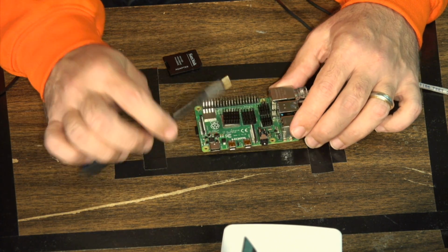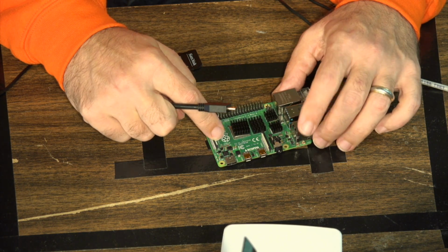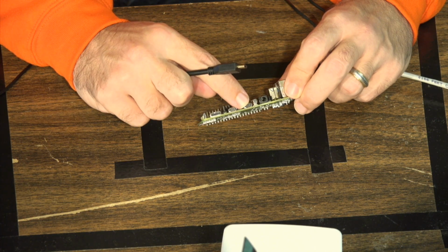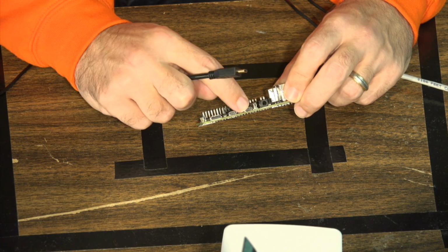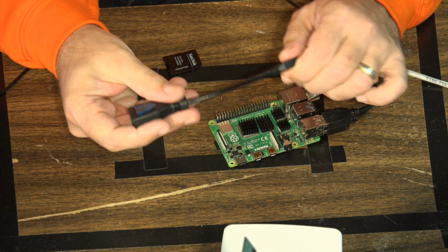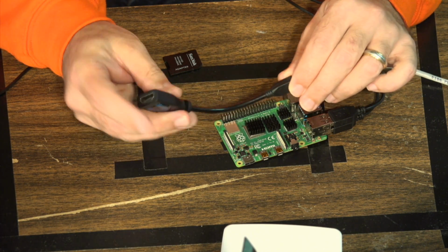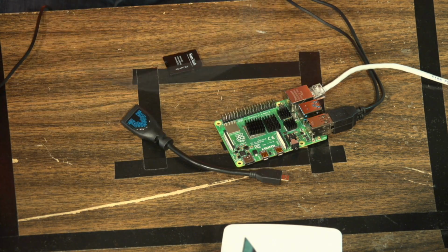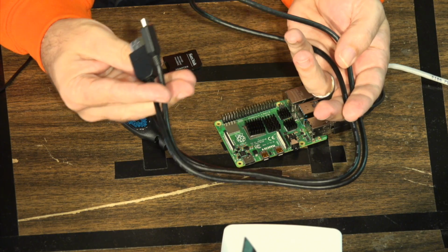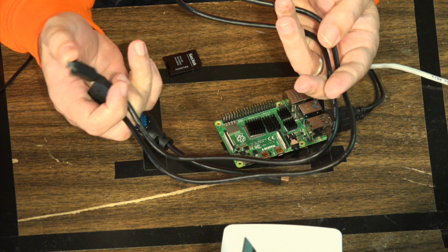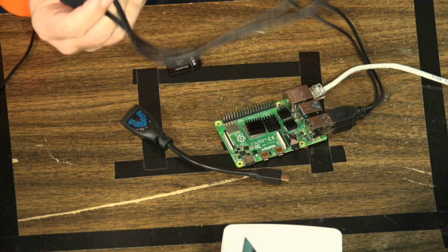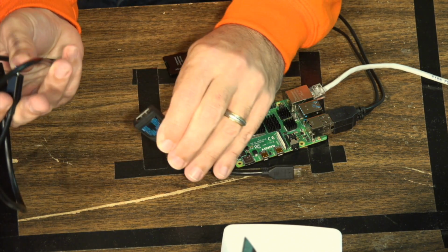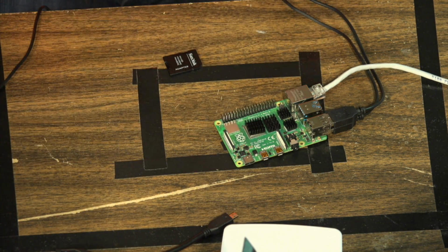Then past that, you are going to need to plug your Raspberry Pi into your screen or monitor. Do remember with the Raspberry Pi, it is micro HDMI cables. So if you have a micro HDMI coming out of the Raspberry Pi, you're either going to need an adapter like this, which is micro HDMI to full-size HDMI, or, because I do all this video stuff, I actually have a cable. You can buy cables that simply have micro HDMI on one side and full-size HDMI on the other. This is what I would recommend that you have. Then you don't have to worry about any problems with the adapter.